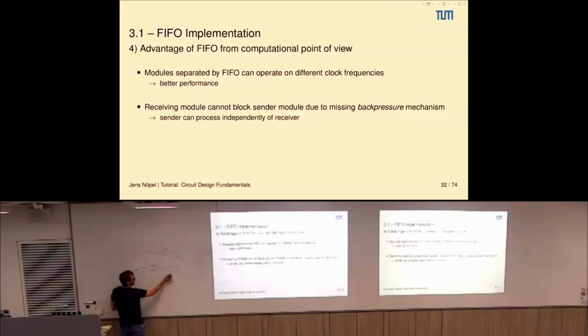But what's also happening is that module B is telling module A that it is ready to receive data. Because module A needs to know at what point in time module B says, okay, I've read your data, and it would only do that if it's ready. And such a handshaking protocol is then this back pressure mechanism. Yeah. So back pressure is, I wouldn't call it a mechanism, even if it's written on that slide. It's just that module B is back pressuring module A.